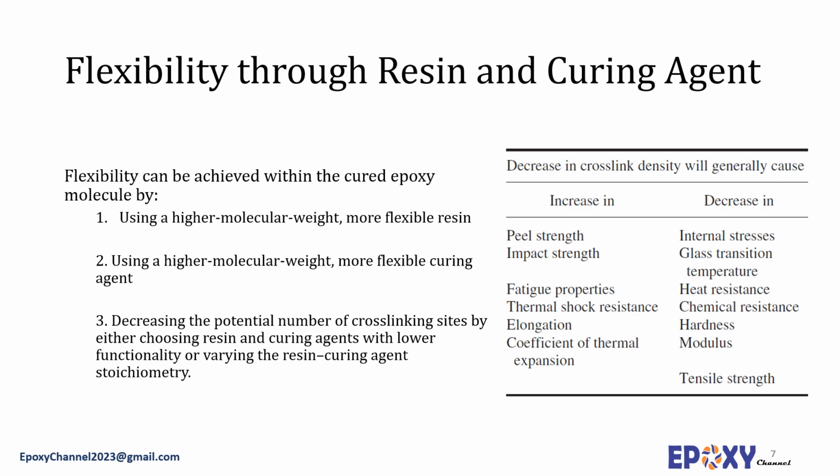The main reason for the greater flexibility is due to long-chain difunctional material that upon cure becomes part of the epoxy resin. The result is a single-phase flexible system. The disadvantage of this approach is a reduction in the crosslink density and consequently a reduction in glass transition temperature as well as the heat and chemical resistance of the system.